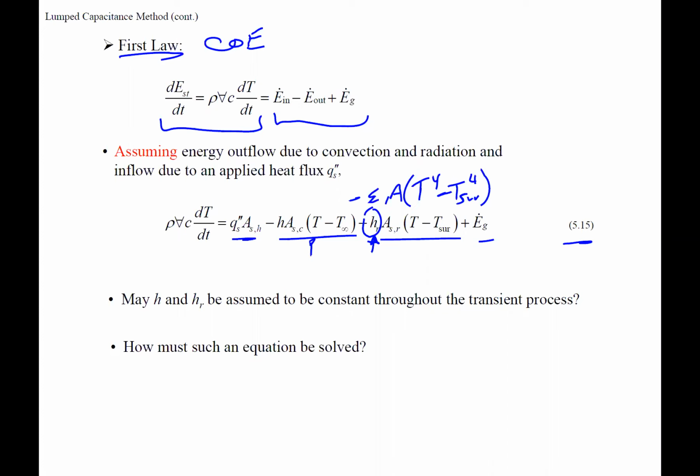So we'll show the situations when we simplify. If we cross some of these terms off, we can integrate. But if we have radiation, which has temperature to the 4th, and any of these other terms, we can't solve it without numerically solving it. Basically, we would have delta T over delta t for this, and we'd have to march in time.